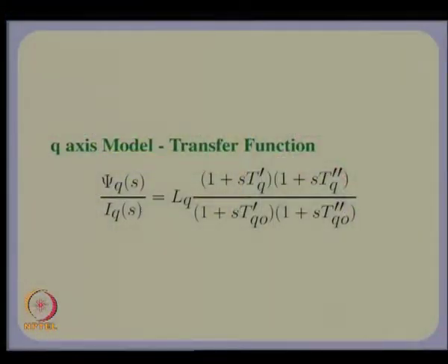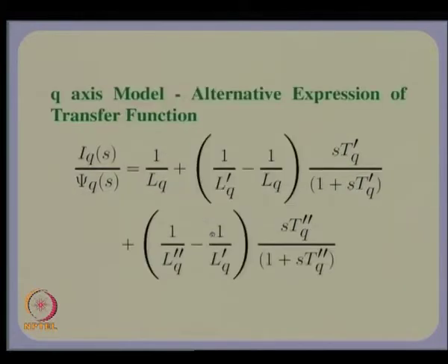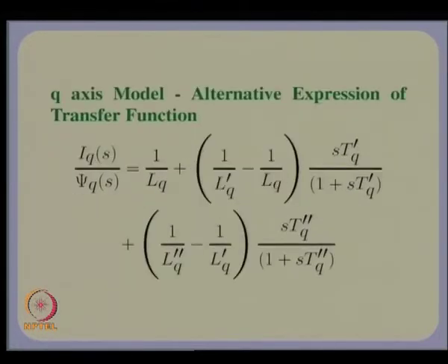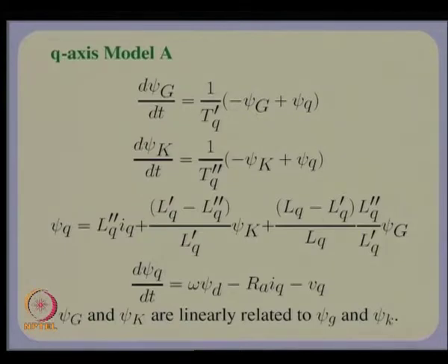Let me just show it to you. You can actually work this out. It is a bit of an exercise, but you can show that this particular state space model will give you the same transfer function relationship between psi q and I q as given here. All you have to do is, for example, take the Laplace transform of the first differential equation, the second differential equation and the third algebraic equation, and you should be able to get this interrelationship.